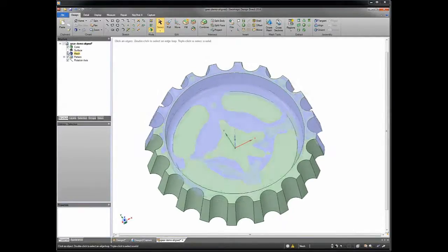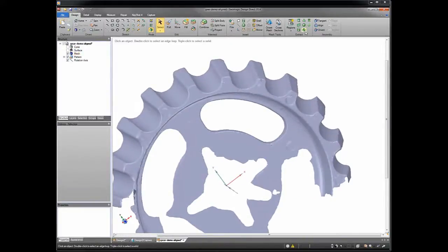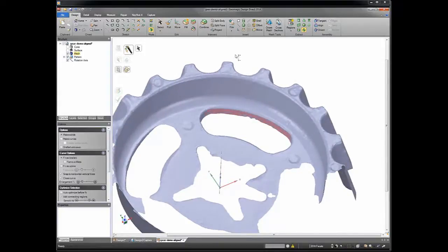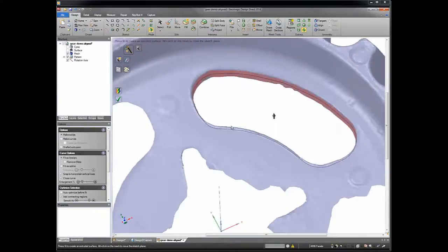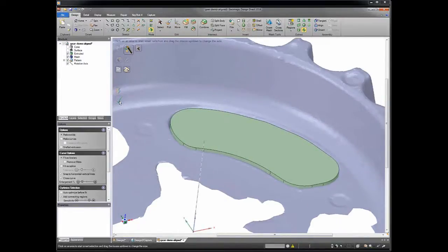which is there's this shallow indentation in the middle. Now, we could go to our extract tool, and we could use a tool like Smart Select, and we could try and see if it's able to actually find that geometry. And it is. You can see there that it actually does a pretty decent job of finding that little plug, that little extruded body. Just a couple of quick clicks, and I got it.